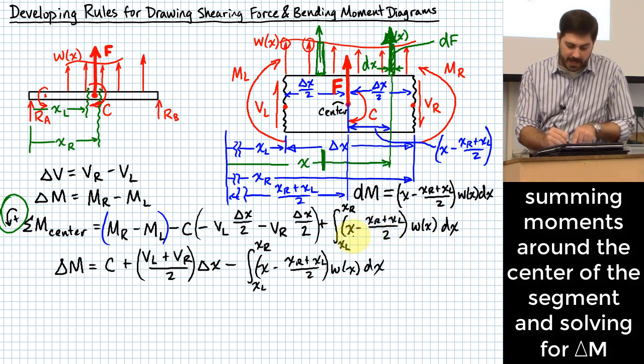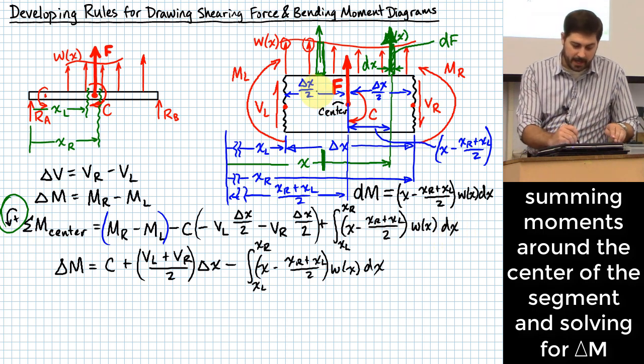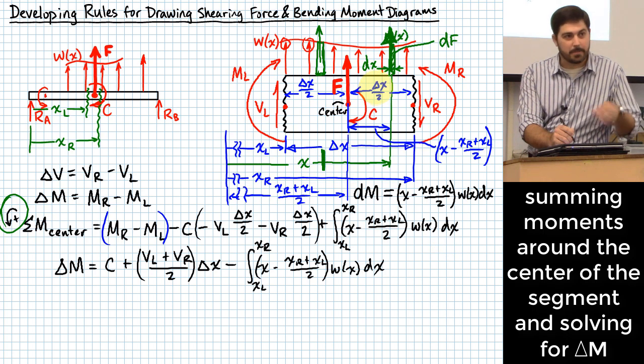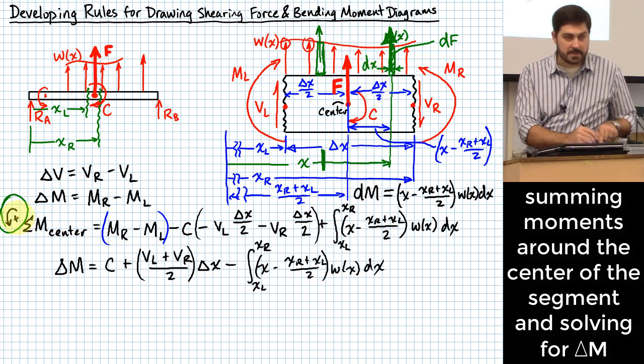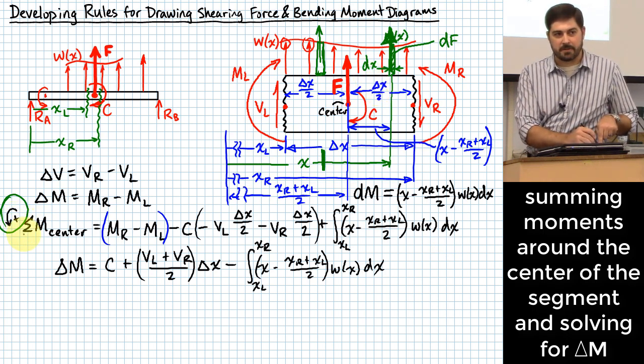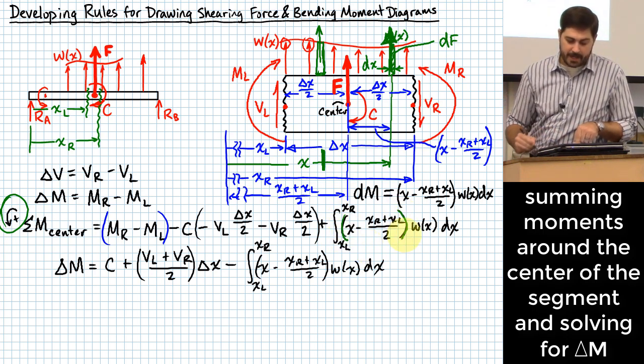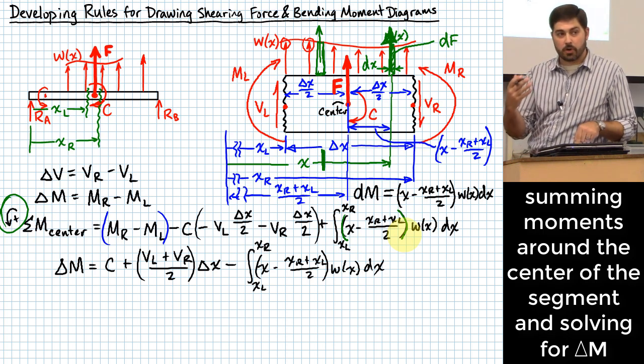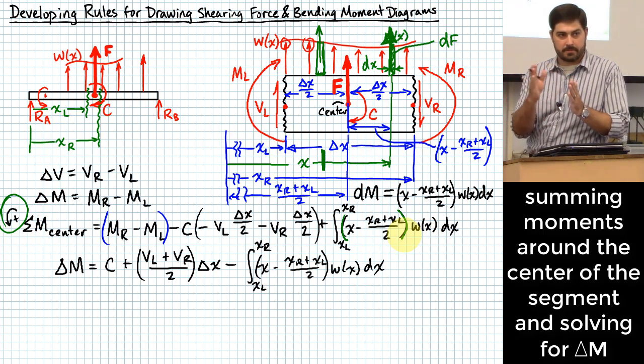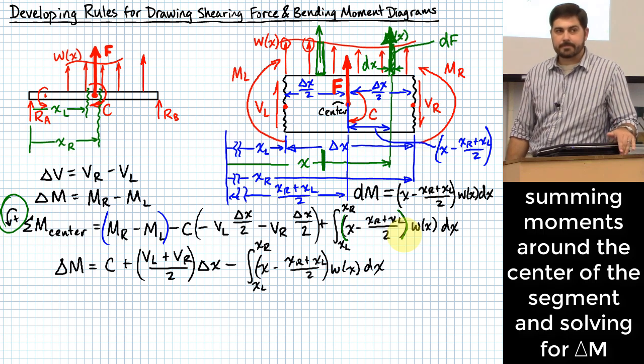So you'll end up with a negative value in the parentheses, times a positive value implied by w of x dx, which would imply a clockwise tendency to rotate, and you'd be counting it as negative, so that would still be consistent with our counterclockwise positive summation scheme. The integral takes care of the entire length because this one term right here keeps the correct sign just based on those coordinates. The sign will change as we progress.